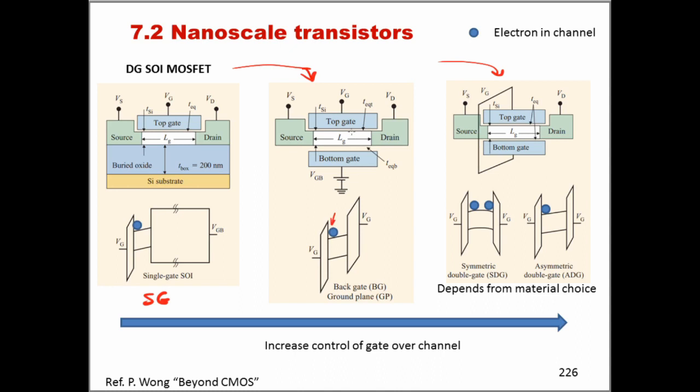So you can see that I can use the double gate in such a way that the charge carriers in the channel move in one localized area, or like in this case, I can use the double gate in a completely symmetric approach in such a way that I'm using two physical locations to let the charge carriers move into the channel when the transistor is on.